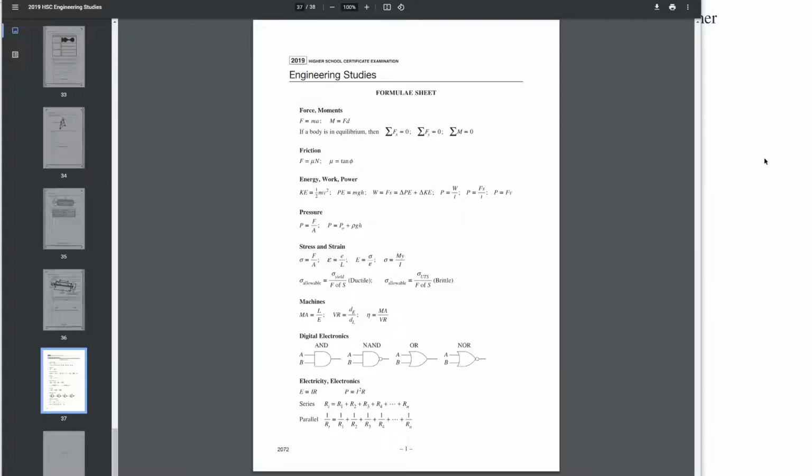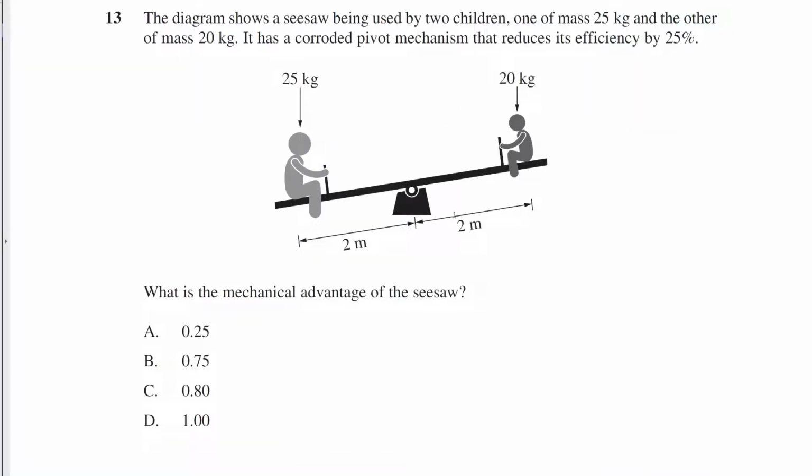Now, in this diagram, what is the velocity ratio? The velocity ratio is the distance traveled by the effort divided by the distance traveled by the load. We can use the comparative radii to make that comparison. What we're really measuring is the circumferences, but because pi is on top and bottom, we can divide that out. So what we have is 2 meters versus 2 meters. And when you have 2 meters versus 2 meters, the velocity ratio is 1.